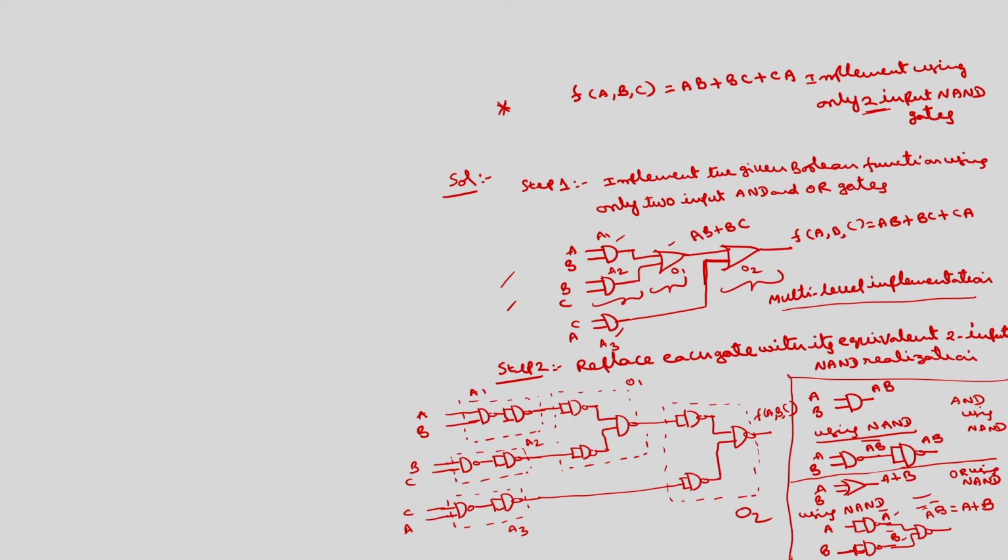Step 3 is, if two NOT gates appear in series, this is in fact a NAND gate, this is not, this is not. If two NOT gates appear in series, we have to cancel them, because if the signal here is P, this is P bar, again here P double bar, which is equal to P, meaning this point and this point are the same. So, these two are useless, we can remove this.